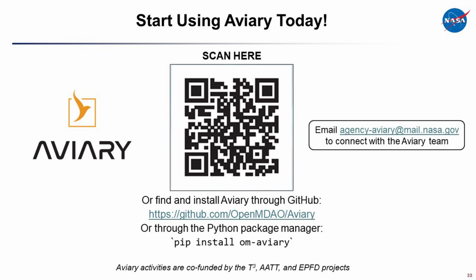Currently we don't have any GUI for that. I have a personal interest in modeling those kinds of vehicles, and I feel like that might be the easiest way to do that. Currently, you would have to do it by defining your propulsion subsystem with a series of OpenMDAO components that are connected together in the way that you'd like, and you hand that collective group to Aviary and say, this is my propulsion system and this is how it behaves. Use this, slot it in. So currently it's pretty rudimentary if you don't do some of those connections yourselves.